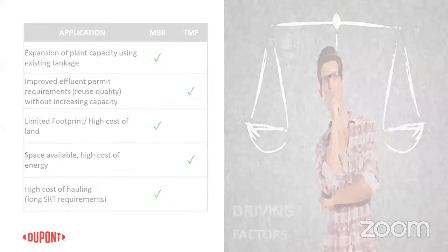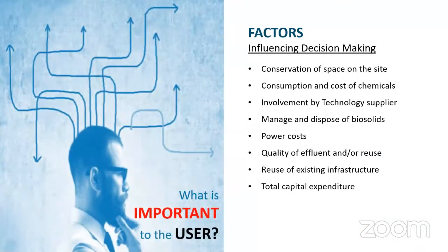So it's not a very challenging option. Of course, what is important? What does a customer, a user, look at? Conservation of space, consumption of chemicals, involvement of technology supplier, management of biosolids and its disposal, cost of power, quality of the effluent and how fit it is for reuse, using existing structure, and total capital expenditure.